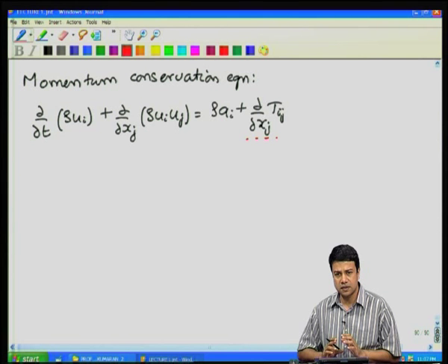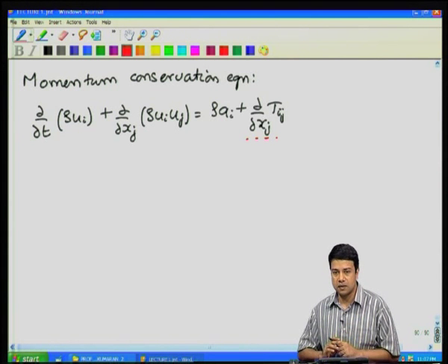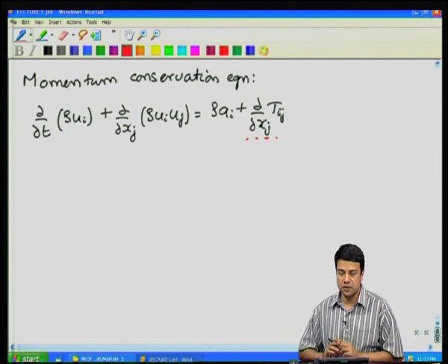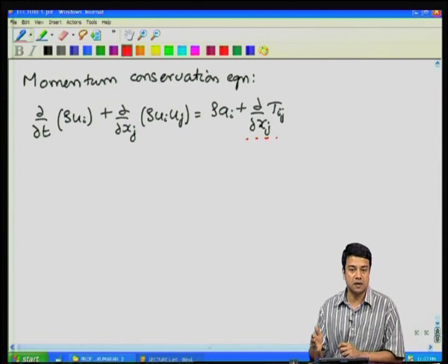Since the divergence theorem is related to the outward unit normal, we will use this notation without loss of generality. If it is defined with respect to the inward unit normal, the stress term here will change sign, but also in the constitutive relation, the equation for the stress in terms of the strain rate, there will be one sign changed there as well, in such a way that the final equations remain unchanged.